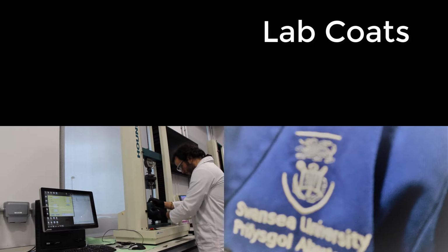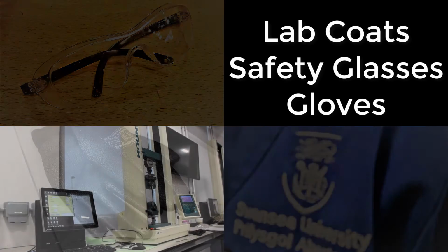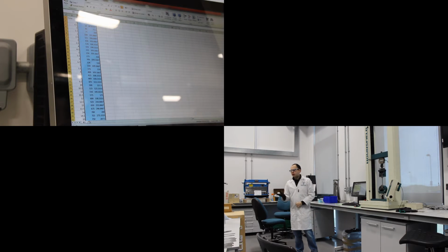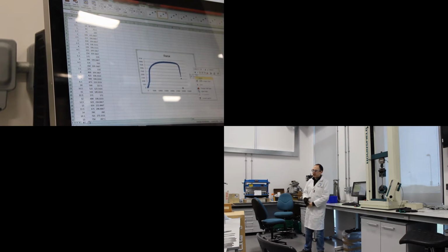While taking part in the experiment, lab coats, safety glasses and gloves should be worn. This will be output into an Excel file. What you then do is convert the force and the displacement into engineering stress versus engineering strain.